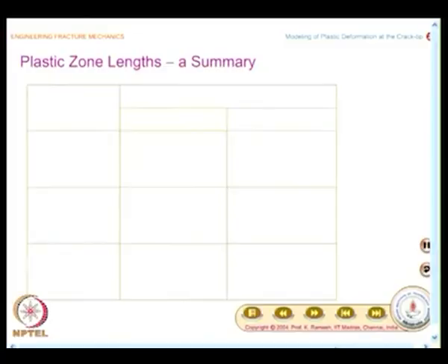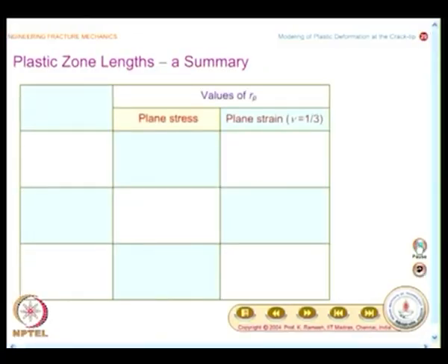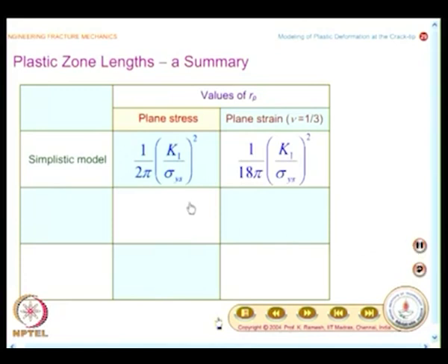That would be a useful information, because we want to graduate from high strength alloys that behave in a brittle fashion to alloys which also have some small trace of plastic zone. You could apply fracture mechanics to that. So, you have a simple via media of modifying the crack length. And before we proceed to the calculation of stress intensity factor, we would have a look at the plastic zone lengths that we have calculated by various methods. We will also look at what way the results are for plane stress and how the results change for plane strain.